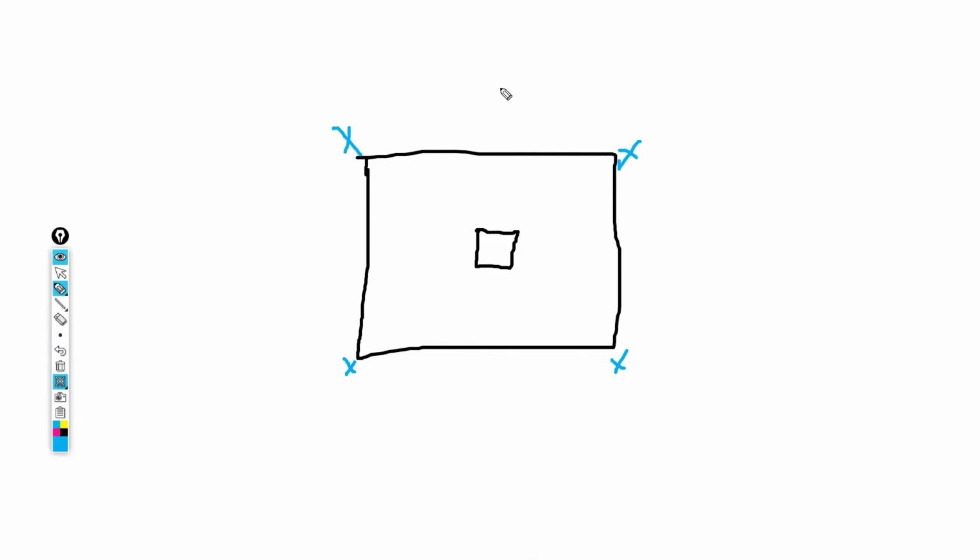At no occasion will you find that the pressure at this point, or this point, or this point is more than 200. You get it? So your foundation design should reflect that. But the moment you reach a stage where it shows that they are less than 200, then that means the foundation is okay. You get it?